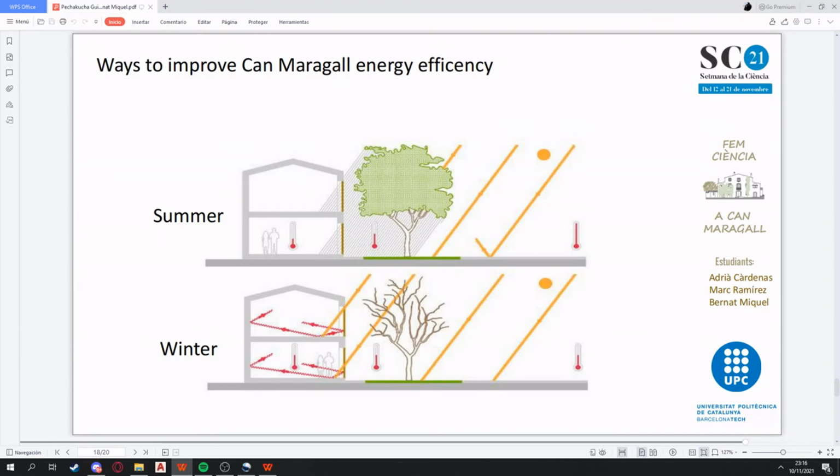The outer temperature and direct solar radiation heat the outer surface of the construction element during the hours of sunshine, which makes this accumulated heat begin to transmit slowly inwards. This implies that you can take advantage of the accumulated heat when the temperatures drop at night.